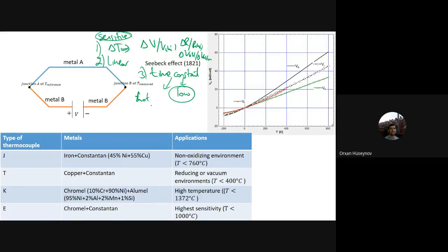Similarly for sensors, say I want to measure the temperature of the room. I put the sensor in the room. I'm trying to measure the temperature, but you wait for a long time and say that after 1 hour, you see the temperature of the room, which is 20 degrees Celsius. But during that 1 hour, maybe the room temperature increased to 25 degrees Celsius. You see, here you are lagging. The sensor lags 1 hour before the real temperature, because it shows the value after 1 hour.